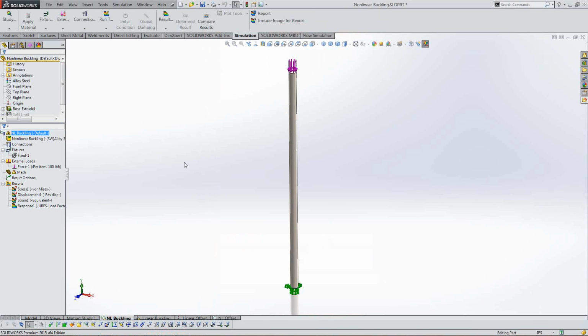It's not susceptible to the types of things that would cause other traditional types of nonlinear studies to fail. For instance, if a force control problem encountered a buckling point, it would fail and it would give you an error saying that it had encountered a buckling point, because it can no longer determine what's happening in the structure. All right, so let's get off that side topic then.